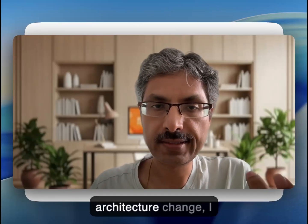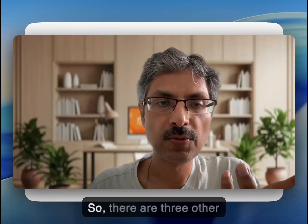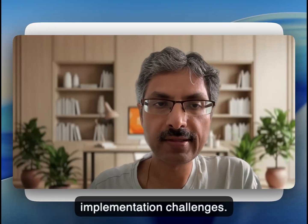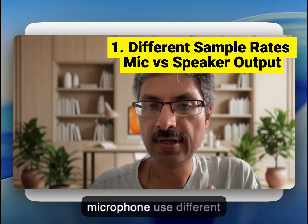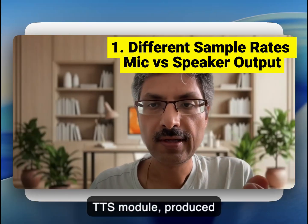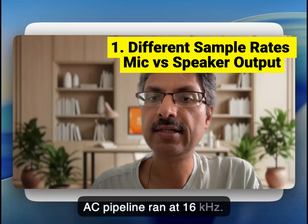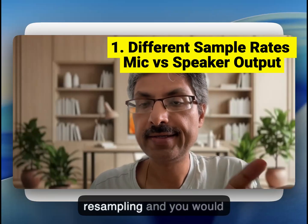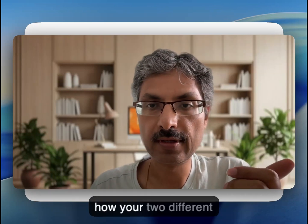Besides the core architecture change, I realized that there are many more nuances that need to be handled. So there are three other implementation challenges. The first one is the generated speech and the microphone use different sample rates. Kokoro, which was my TTS module, produced audio at 24 kHz while the AEC pipeline ran at 16 kHz. So I added real-time resampling, and you would have to add it depending on how your two different sample rates differ.